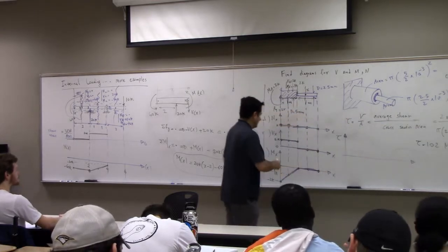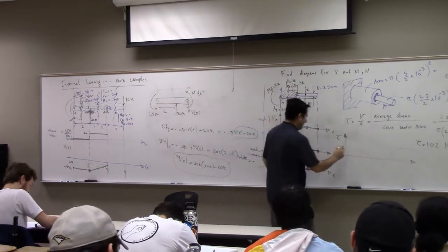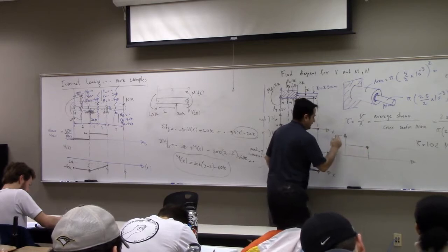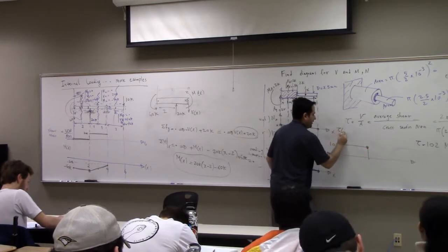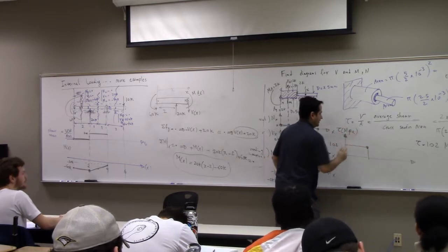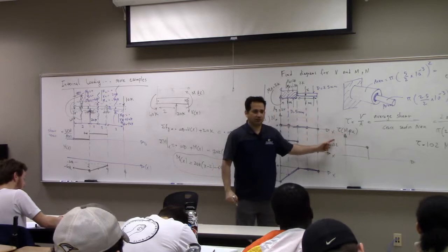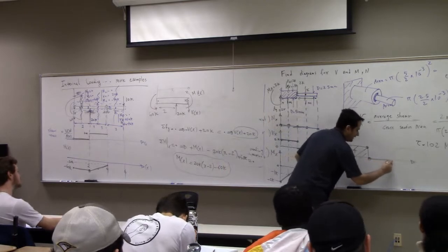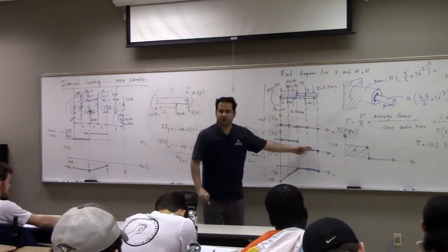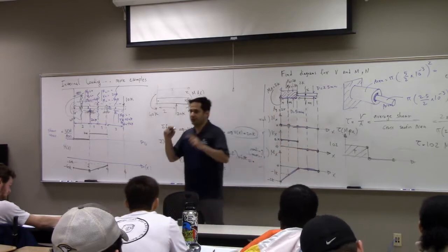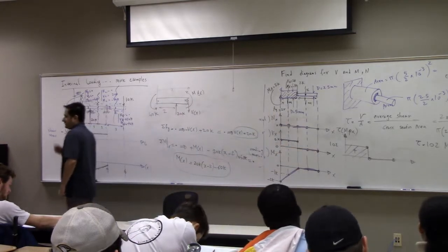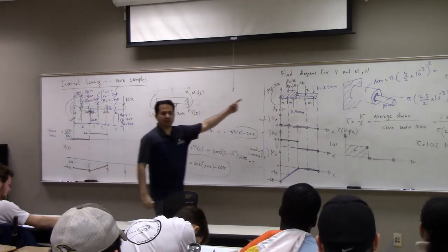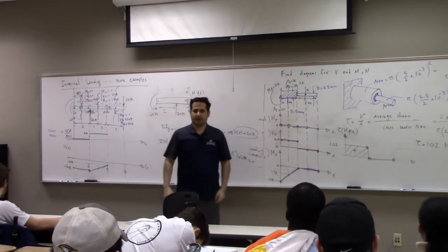So if I want to draw it here for average shear force, from here to here I have this value, 102, and you say tau in megapascal, MPa. So this is 102, positive. And then what do we have from here to the end? Just 0, because the shear force is 0. So the conclusion is the hard part is to get the shear, bending, and normal force diagram. Once you get those, the rest is just simply a scale. You just divide it by area, right?